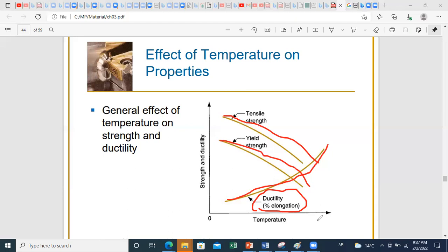Okay, so we should try to have an easy deformation to not have large forces, but at the same time we should have final properties for the materials that are acceptable. So it depends on your application. What are your desired final mechanical properties? This will allow you to decide on which temperature you can use to perform your deformations.